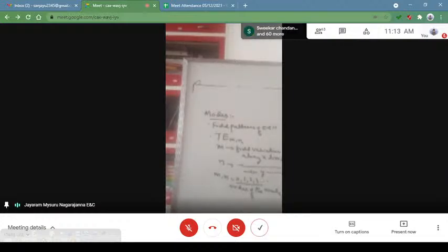One important thing: if you look into the equations of the field that we have represented, since they involve sine and cos functions, if both m and n are 0, all the field components will be 0. No field component will be present in the waveguide system.